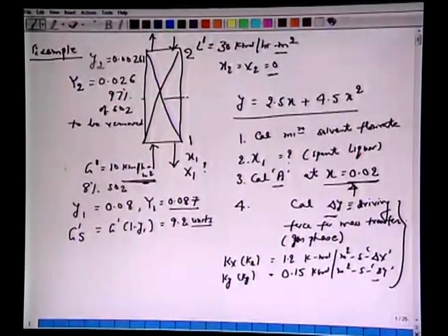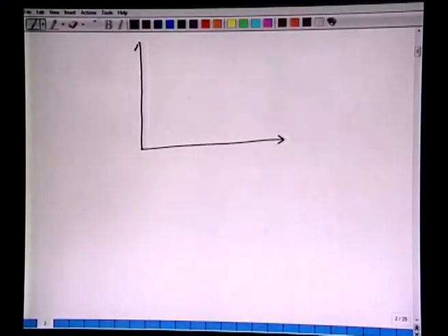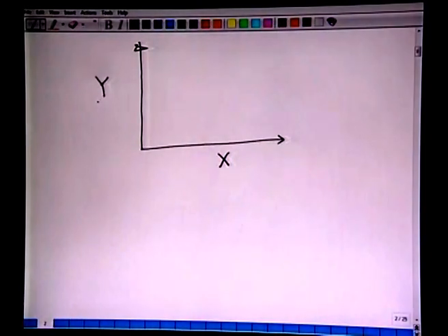So all we have done, let's start here. We have marked our coordinates y1, here we have x2, here we have y2. We know this equilibrium curve. All we are supposed to do is draw this graphically. So let's do it graphically. We have capital X and capital Y. That is the way we have been working, doing the calculation on a solute free basis.